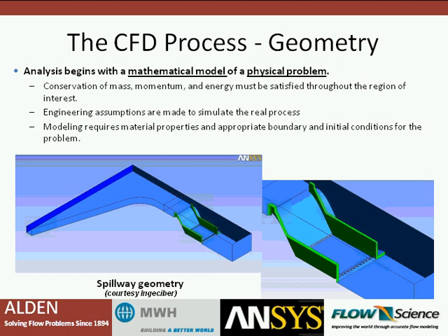So now going on to the CFD process itself. The first step in developing any problem is to develop a mathematical description, which includes the equations of fluid flow, heat transfer, mass transfer, etc. Primarily for today, we're really talking about fluid flow in particular. Another key component is a representation of the flow domain in a digital format. This may come from a CAD tool or be created from scratch in a geometry tool. One also requires knowledge of the material properties and initial and boundary conditions for the system.